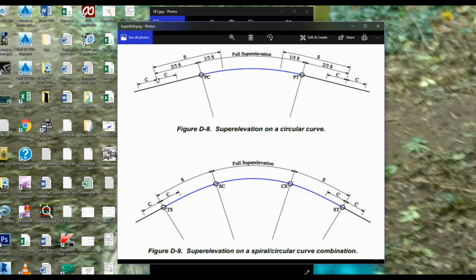So that would give us the chainage there by subtracting the whole of it from here to there. And similarly, what we'd do is we'd add it to the chainage there to take us to the chainage there. So that would give us our 2/3 into the straight.